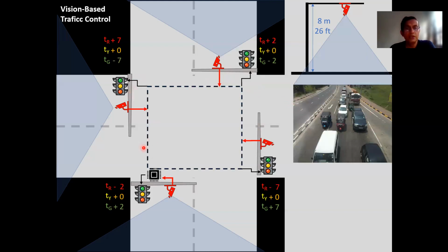And as I said, they are wired and they are connected to one single junction where the PLC is located, where signal control is located. Even though the signal controls are distributed around the junction, the controller is just one and it is somewhere here. Then you have underground cabling to connect these PLCs and then you can control these lights. So our new unit, the adaptive traffic controller, is going to be next to the PLC control board, the small white box you can see in junctions. This is where the PLC is.